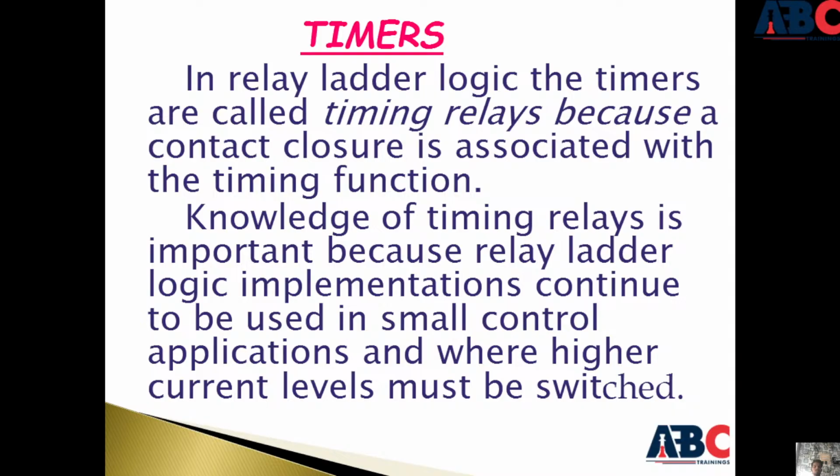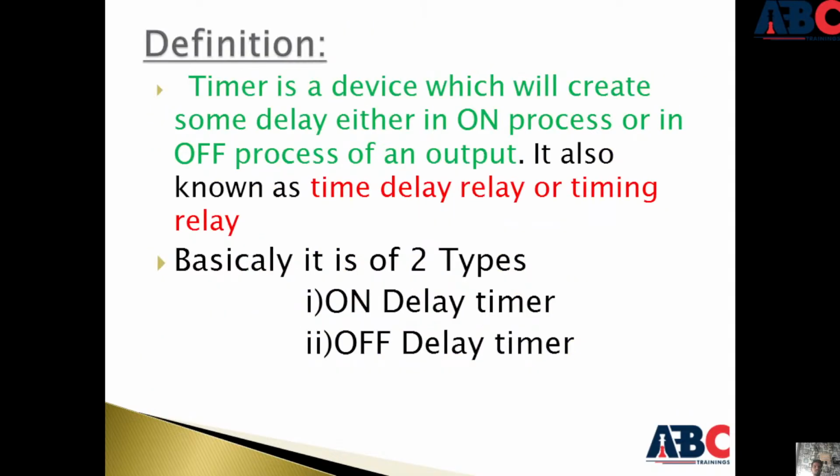Knowledge of the timing relay is important because relay ladder logic implementation continues to be used in small control applications and where higher current levels must be switched. Definition: a timer is a device which will create some delay either in the on process or in the off process of an output. It is also known as the time delay relay or timing relay.